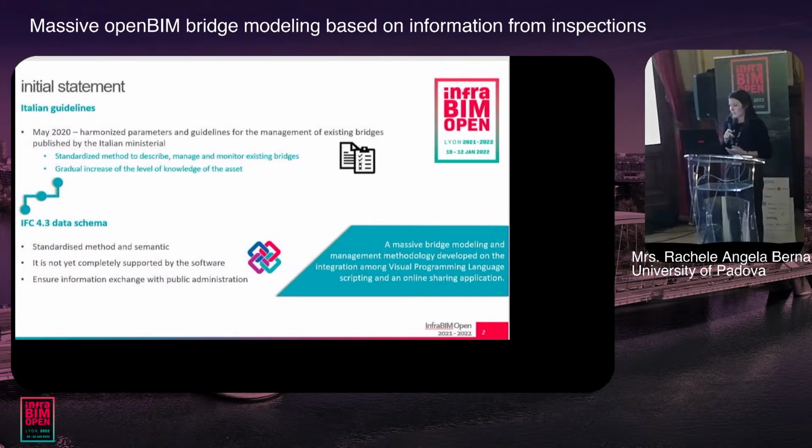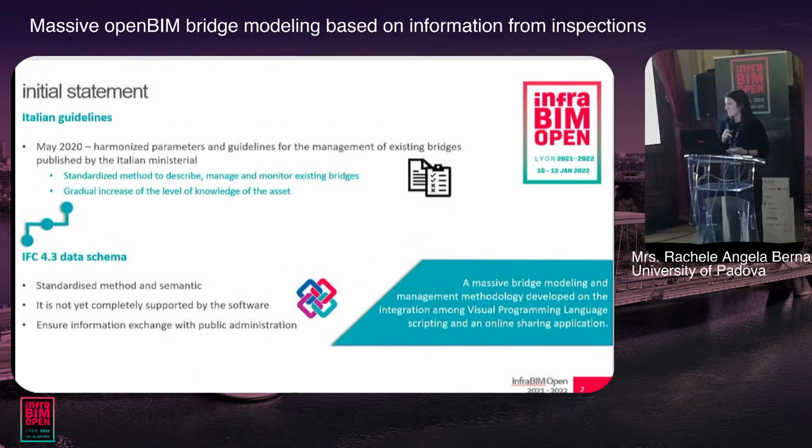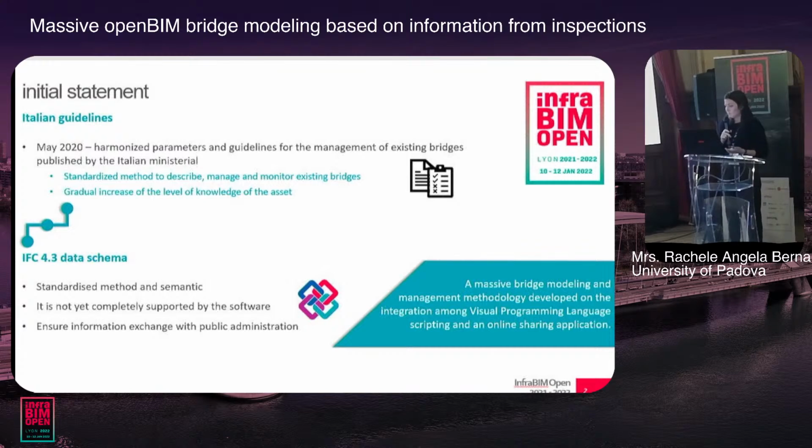And the other approach is the IFC schema, and from these schemas we use, of course, the methodologies, the taxonomy, and the relations between objects. Although it is not yet completely supported by software, knowing the development process of IFC 4.3, it can ensure the information exchange with public administration, and also because in Italy it's mandatory to use open formats for projects related to public assets.